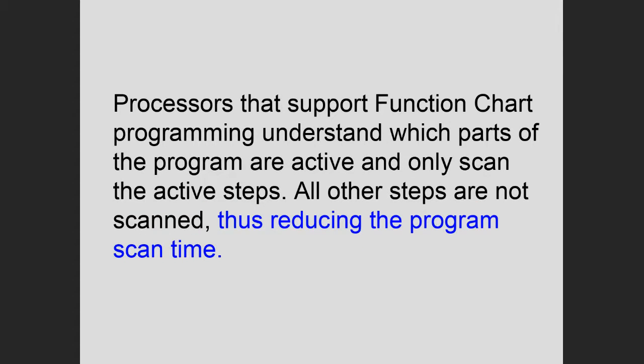Here's another advantage of using this method. Processors that support function chart programming understand which parts of the program are active and only scan the active steps. All other steps are not scanned, thus reducing the scan time. We talked about scan time. You know how important that is.